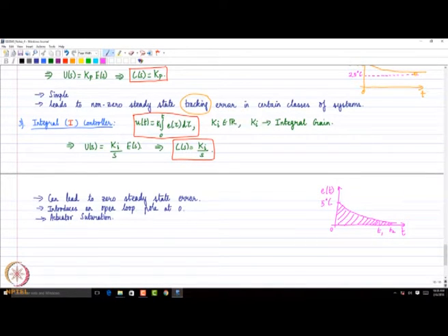With such a controller, although in theory I might be satisfying some performance requirements, in practice I would not be able to reproduce them. I may say settling time would be so much, and peak overshoot would be lower than, let's say, 5% if you give 1000 newtons, but the capacity of the actuator is only 100.